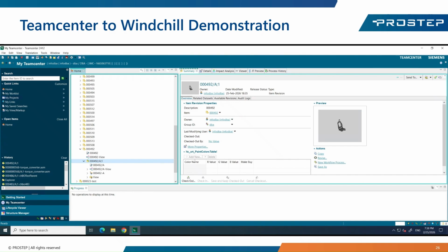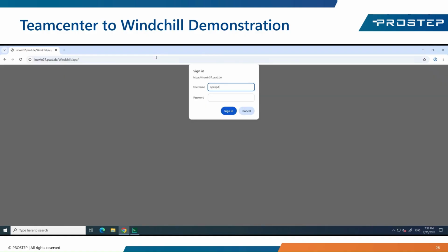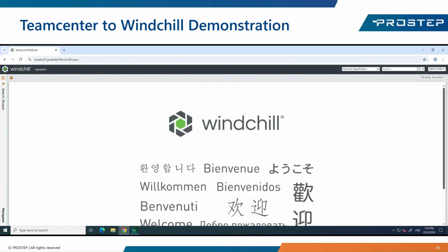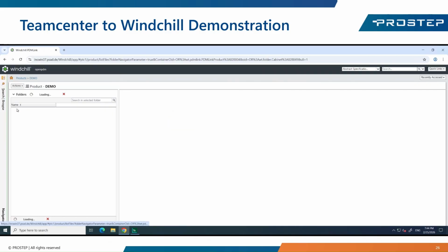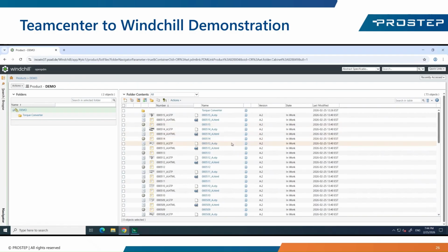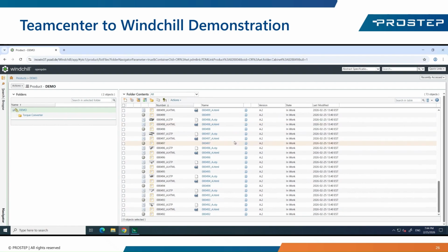We have other deviations from this workflow as well. Depending on what your use case needs are, this is not a one-size-fits-all process. So if you would like to generate Creo from the STEP data, then you can go ahead and do that. That has an advantage of carrying over some of the structure. And we've got another demonstration that we're putting together right now that's doing that, so that you can then have the product structure available in Creo.